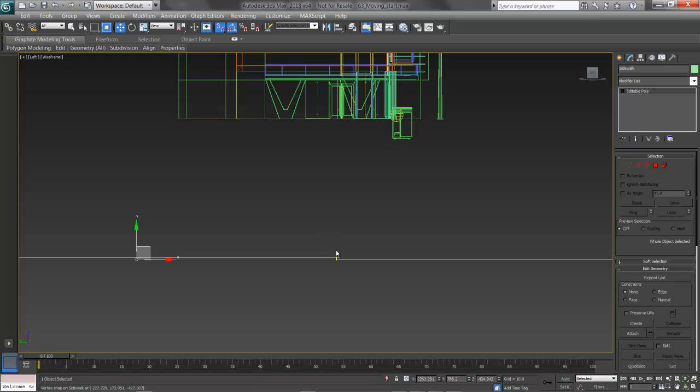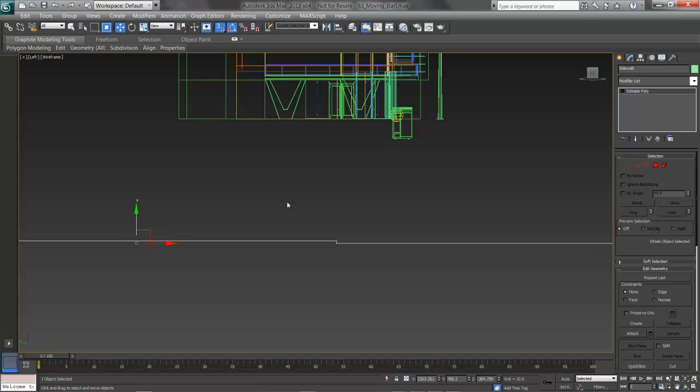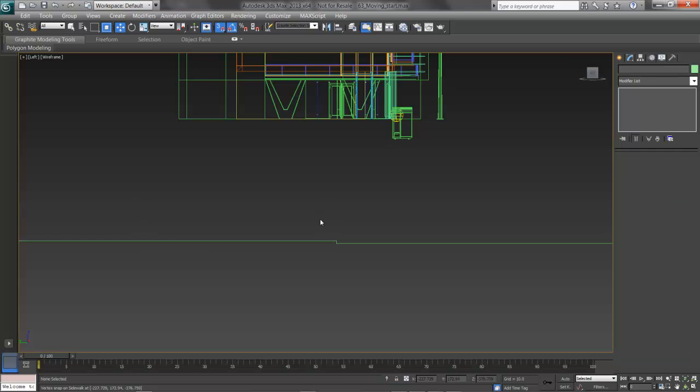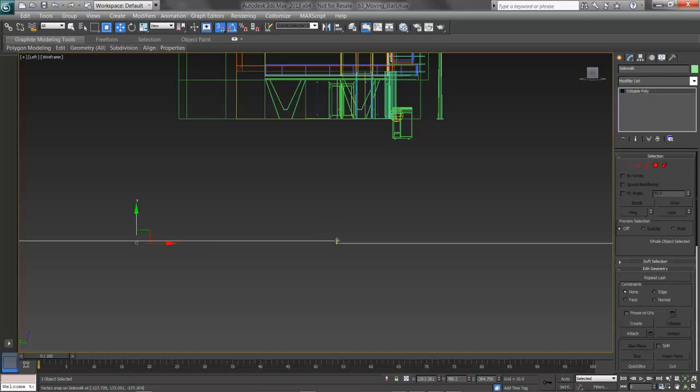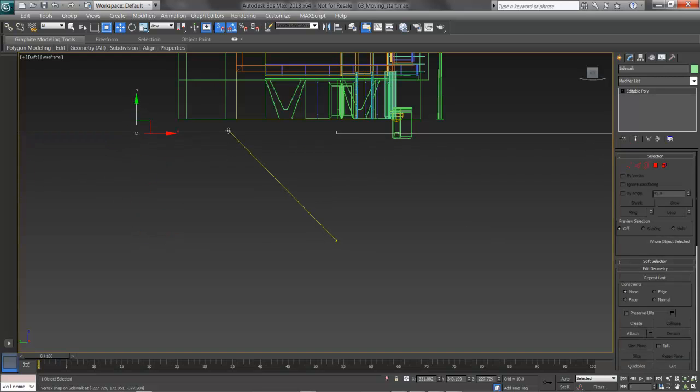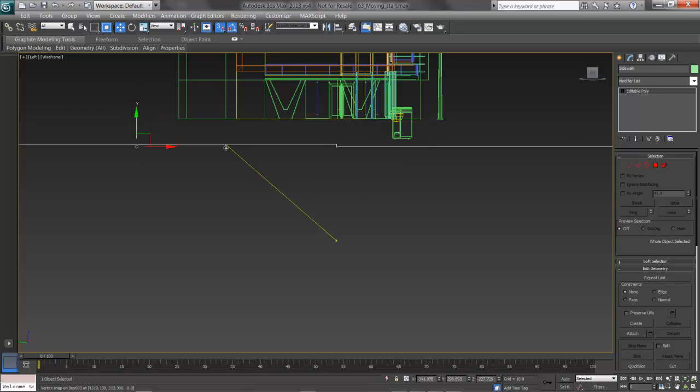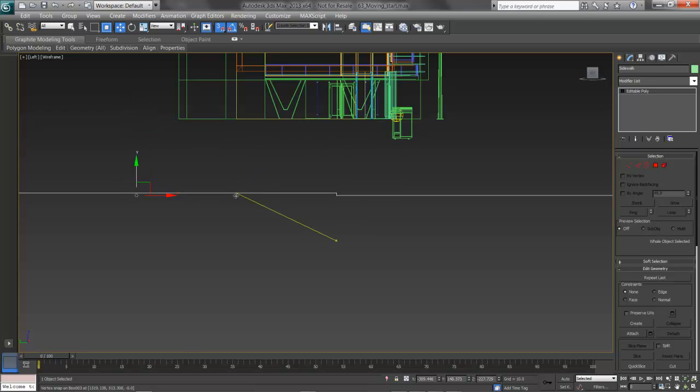Now I'm going to register this right here on the curb, and we can see that yellow plus indicating the snap is registering. Before I do that though, I'll click and drag on just that Y-axis to make sure the motion is constrained on one axis here. And I'll pull this up, snapping right onto the building. Now if you noticed here, my snap didn't go the first time and it actually deselected the object.